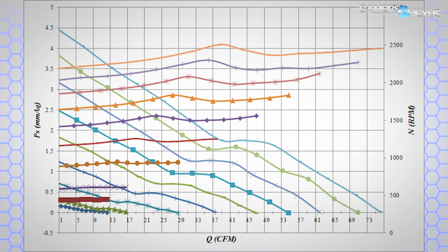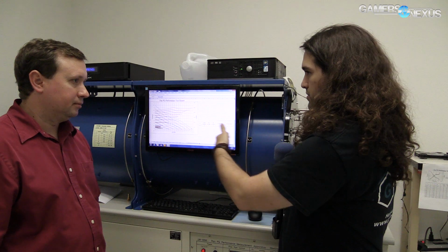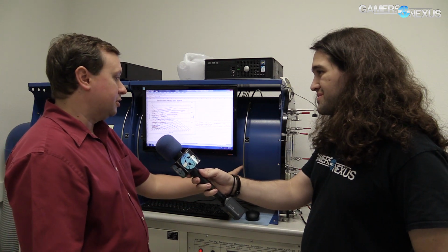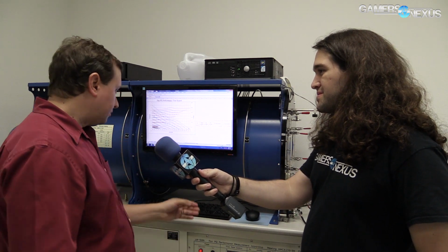Mechanically, let's walk from this end to that end. What's going on inside of the wind tunnel? So let's back up just a smidge. Here is the plate where we mount the device to be tested, a fan or a radiator. I've even hooked up whole cases to this thing and measured flow resistance in cases. This ring right here is attached to 4 pressure taps. This is the static pressure sensor. It measures this in relationship to atmospheric pressure outside of the room.